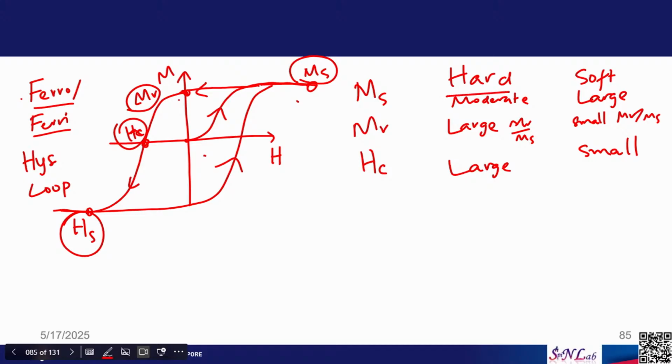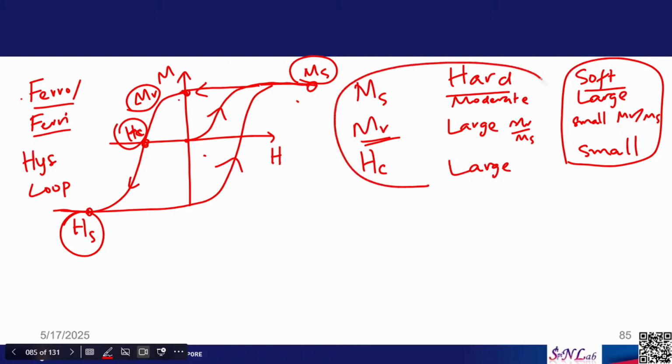For example, soft magnetic materials have their own use in transformers, in the writing heads of hard disk drives, and in electromagnets. For all these applications you need soft magnetic material. Hard magnetic materials can retain the magnetic polarity, so you can use them in motors and any application where you need a permanent magnet, and you can use these materials for storage, memory.